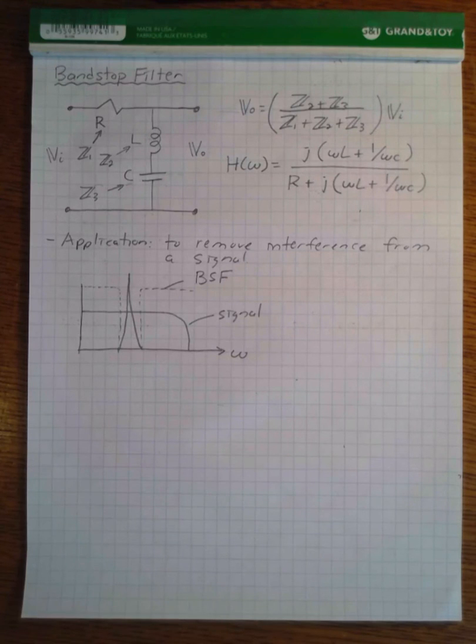And so this concludes our discussion of passive filters. There's just one point I'd like to conclude on. At the start, I mentioned that there is such a thing as active filters with transistors and op amps and stuff like that. And it's also possible to create filters that consist of a larger number of resistors, capacitors, and inductors. And those filters we refer to as higher order filters. So for example, you can create a low pass filter with a number of resistors and capacitors and inductors even.